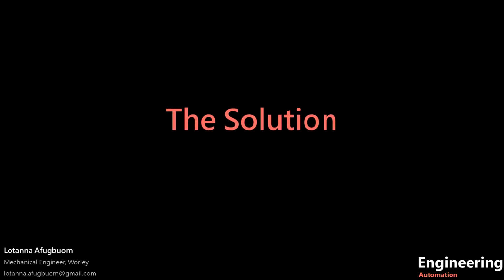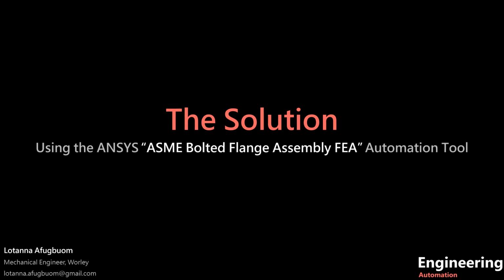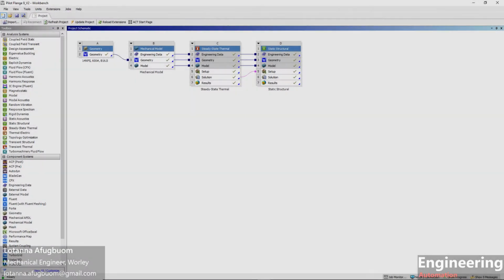This solution section is split into 2 parts. The first part describes the manual process of building the FEA model for a flange assembly, while the second part shows the use of the automation tool to generate the FEA model. The finite element analysis model outlined in the ANSYS Workbench application begins with the geometry component where the CAD model is developed.